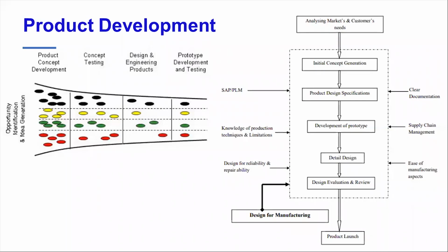So kind of impact loadings, which are typically taken in the form of G loads. So all these requirements. What customers or the market tells you basically is, I want the tank of this capacity. I don't want the tank to fail when there is a vibration. I don't want the tank to fail when the truck meets an accident, and so on.